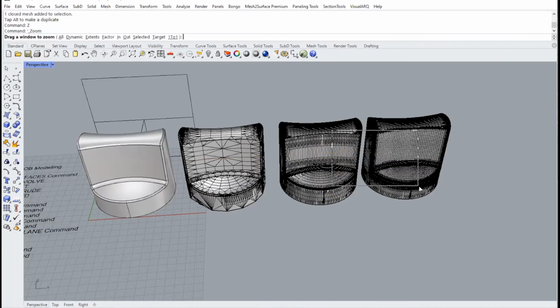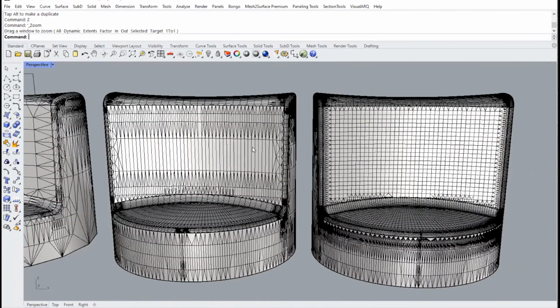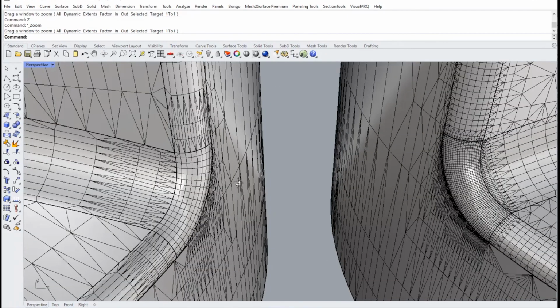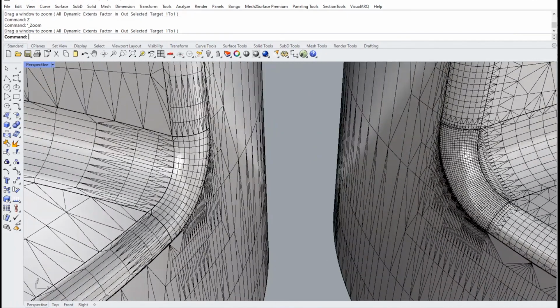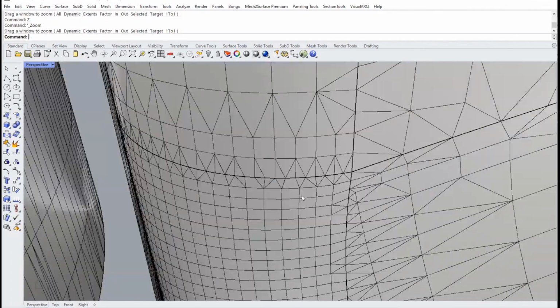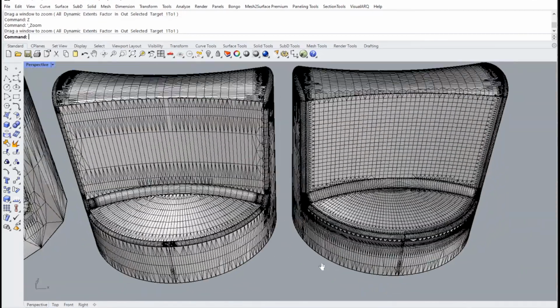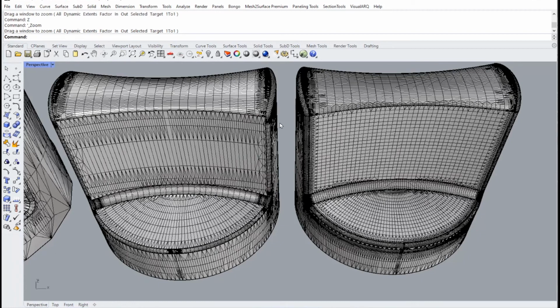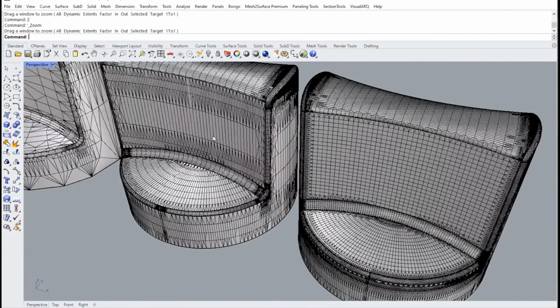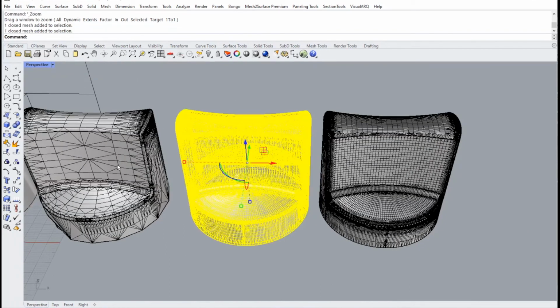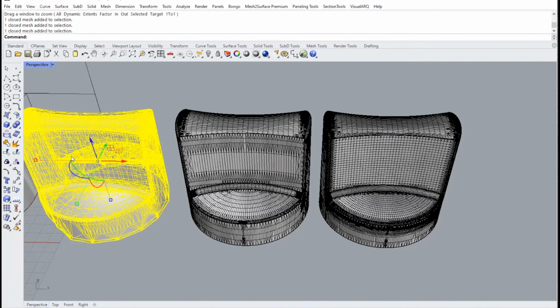It remeshed it, but in a more even way. If I put 1000, you can see the difference in these fillets here. It intensifies the meshes here in thousands. If you want to do that, otherwise you can just slide to more polygon count and leave this. One last bit before I export this for printing, which I will print, and then I'll show you in the images as part of it.